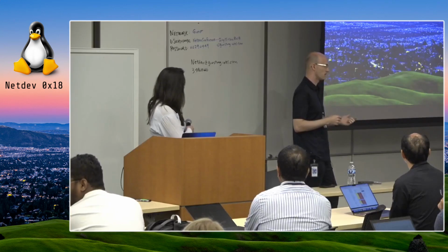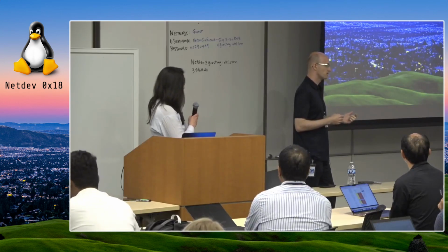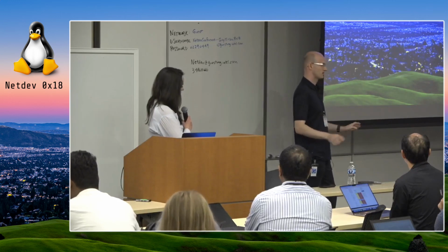The PCIe bus is not meant for time critical operations. So when you send a request to get the time, it is scheduled somewhere on the PCIe, and you don't know how long it will take to receive it back. Like I mentioned in the previous talk, the optimistic way is that it will happen in between our system clock reads if we don't have any hardware acceleration. It never happens like that.